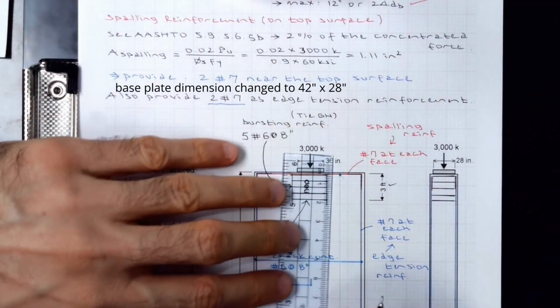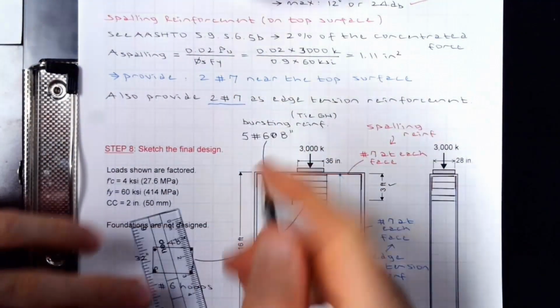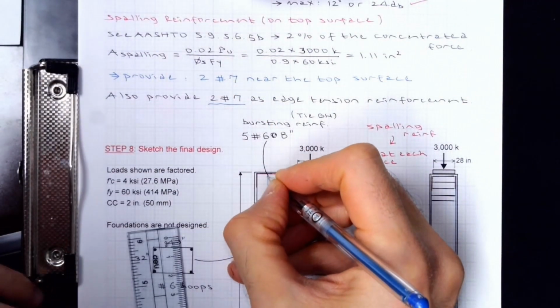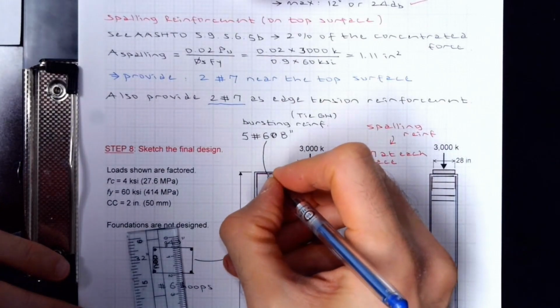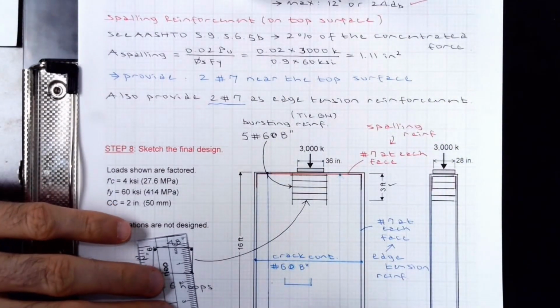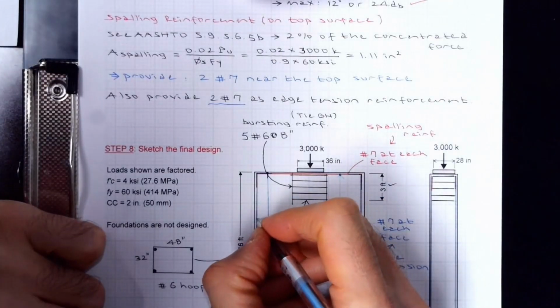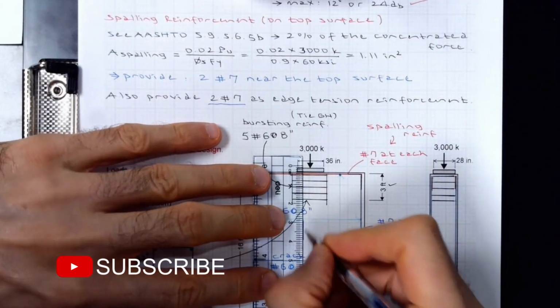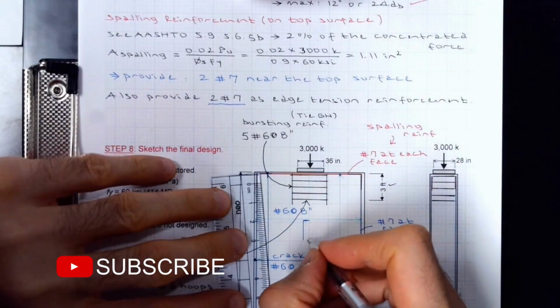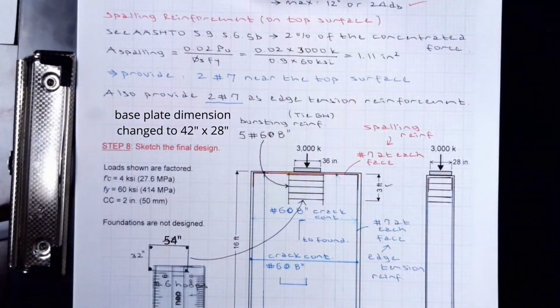The other one would be probably it's going to be extended into the foundation, which I'm not showing in this. Would like to hook this again, 90 degree hook through the thickness, send it inside. This is going to occupy the entire section width. In terms of how it looks, it's going to be probably one hook, the other end would be to foundation. So pretty well done. That's pretty much it from me today, everyone. Thanks very much for your attention.